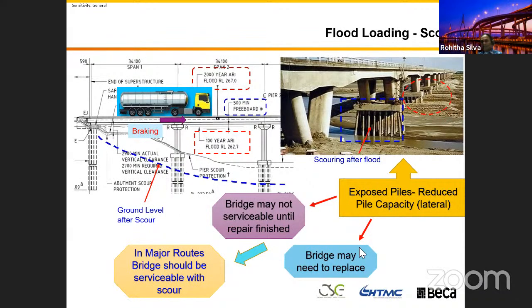I got the opportunity to get involved after the 2011 flood in Queensland, to go and work in the Queensland office when I was working at SMEC. I was able to look at some of the bridges damaged by flood. The bridge superstructure and substructures were serviceable, but because of the significant loss of cover, we recommended to the client that it's not serviceable at this stage and they have to replace the bridge. Yes, we need to make sure that we are designing the bridge for that.